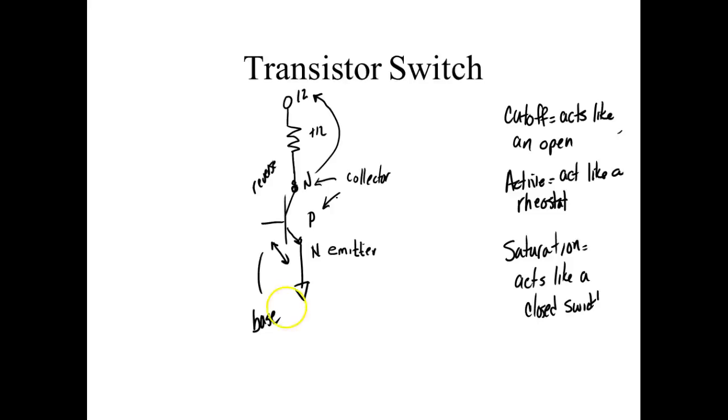So we've got two options. We've got to make sure this guy right here is at least 7/10 of a volt more positive than the emitter for silicon, and that's all we're doing. I could literally come up here and put a voltage over here. Let's say I put plus 5 volts.